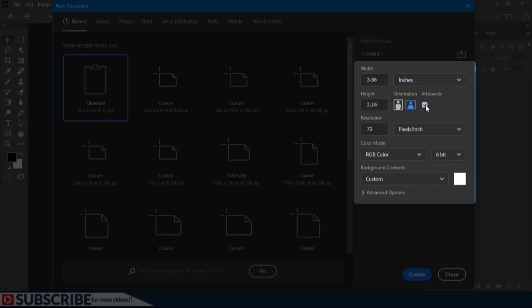Then I'm going to enable Artboard, and as you can see, this is not the standard resolution for printing. So change 72 to 300. What this simply means is that for every inch, there are 300 pixels, and they will be enough to give you a good quality print.